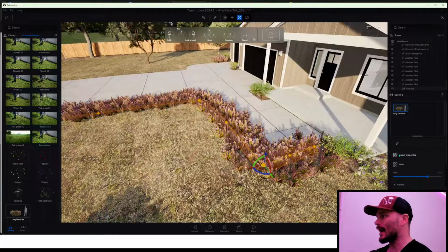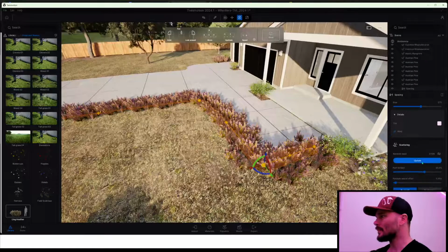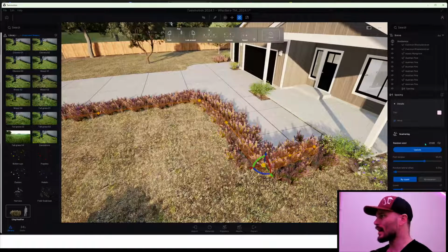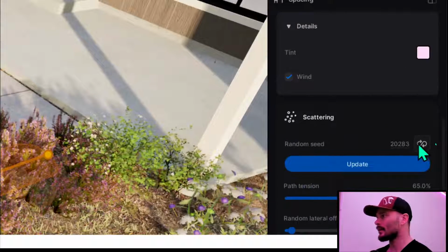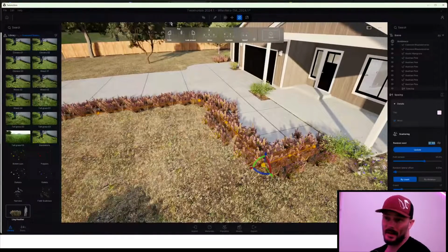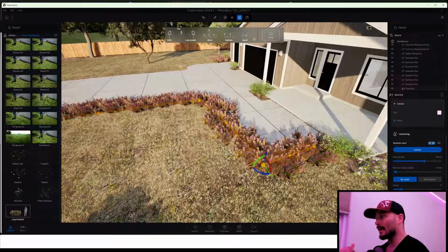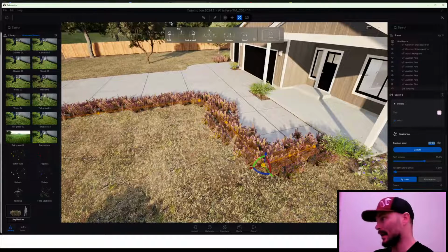And then if we select the ling header in the actual spacing section, we suddenly get this tab, Asset Properties. And so we can change the size of the asset. We can kind of scroll this down. We can still change the tint of this asset, right? And then there is a random seed you can generate. You can just click on this button to generate a random seed, or you can actually key in a seed if you know a particular style that you're using in a different scatter and you want to mimic that. You would just copy the seed and paste it here.